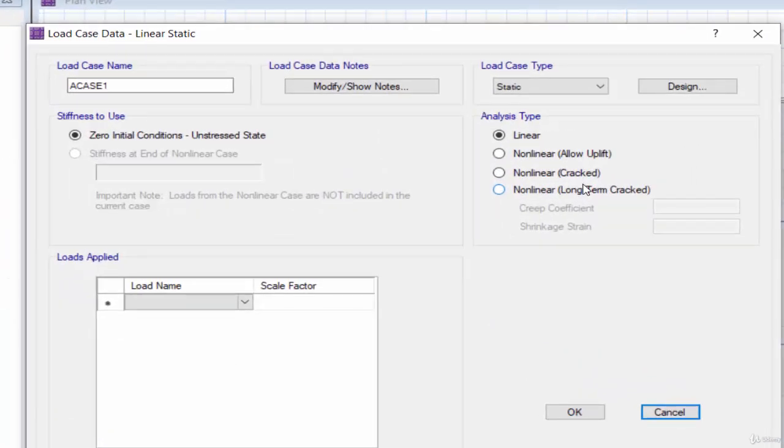These are the steps to calculate the deflection, and we must know that we have a short time deflection and a long time deflection. Short time deflection is due to the self weight of the structure. Long term deflection is due to shrinkage of the concrete, when water goes out from the concrete, so we have cracks, so we have shrinkage. And creep is the cracking of concrete due to constant loads with time. So when concrete is tired, we have creep. We want to define short-term and long-term deflection and check how much the deflection of this slab is equal to.